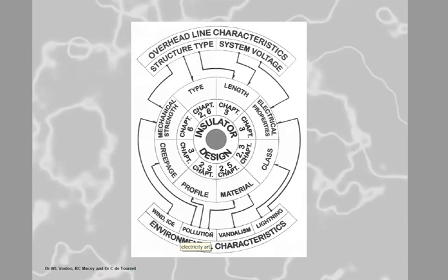Cool. Now, the thickness of the pollution layer. The thicker the pollution layer, the larger the area available for current flow. So A becomes bigger. If A becomes bigger, what happens to R? Smaller. R becomes smaller. What happens to I? I goes up. What do you want? I as small as possible. So you wash, you clean, you get rid of the thickness, you reduce the area available for current flow. Cool. So for L, increase creepage, and for A, you reduce.